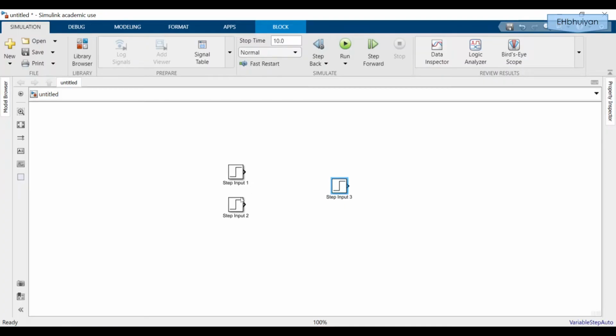Let's say, for example, that I wanted to have step on one line and input on another line in the title. Let's see how we can do that. So let's double click here. Let's say I wanted step, and then I wanted input 1 to go on the second line. What I can do is I can simply press shift enter, and then the cursor will move down to the second line and I can type in input 1. So you can decide how you'd like the name to show up.